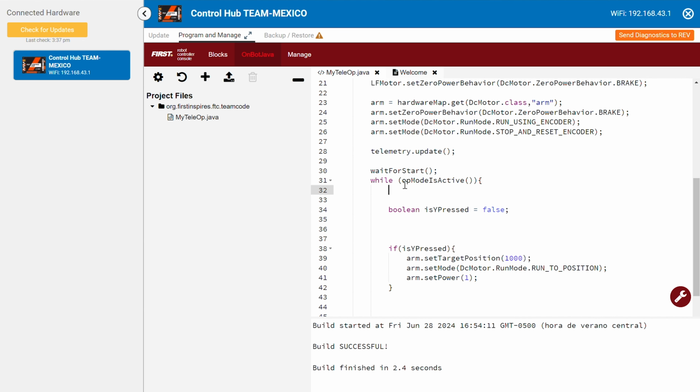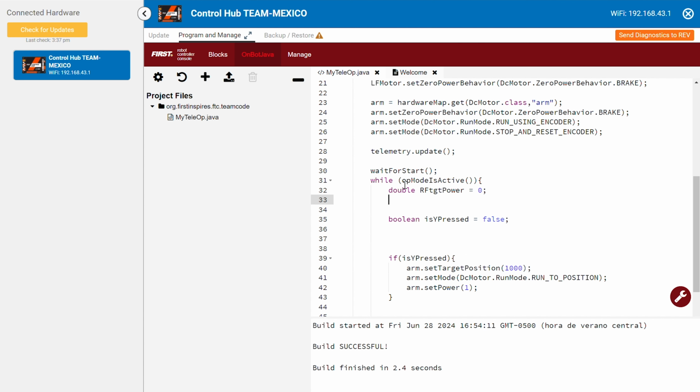Now we are going to move to a chassis of two motors. Do the same process, declare the motors, and on the button bindings we are going to use a method for the joysticks instead of a boolean. The joystick's value ranges from -1 to 1. Depending on what direction the joystick is at, you can do the configuration with the X or Y value of your joystick.